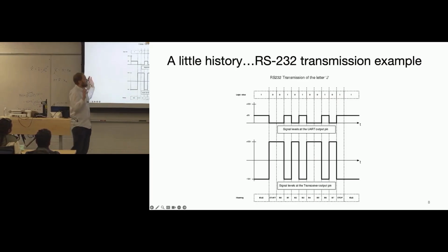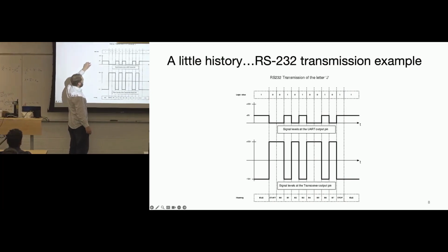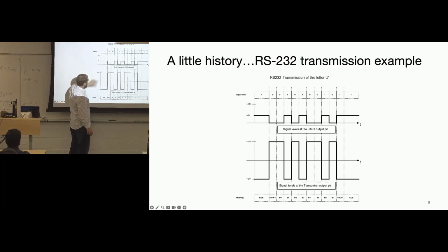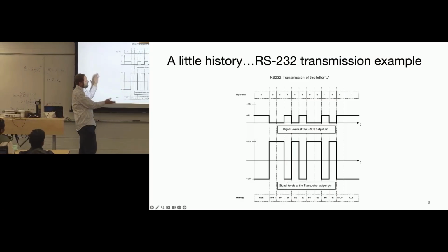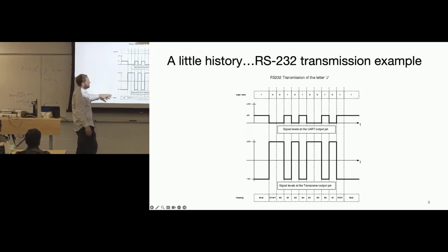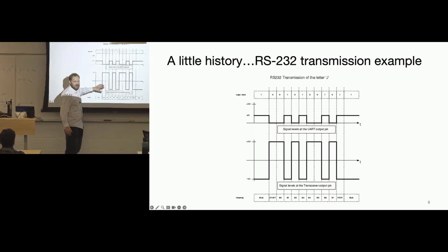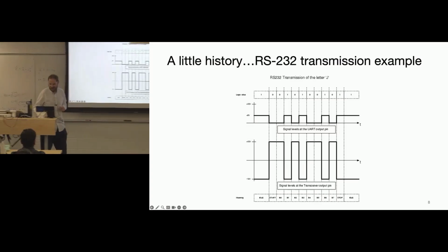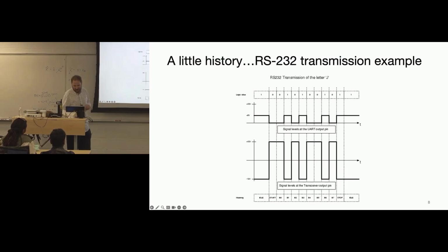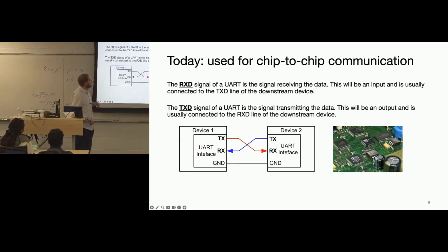How would that happen? Well, what they're doing is they take signal levels, so like 3.3 volts, maybe 5 volts, and they kick it up to plus or minus 12 volts, and they just invert it. They send it literally through an inverter that just boosts the signal up so that it's loud enough so that by the time it gets over to the receiver, the signals have not degraded too much to noise. So it just took me an embarrassingly long time to realize that all that was inside that little piece of converter was an inverter that had minus 12 and plus 12 rails.